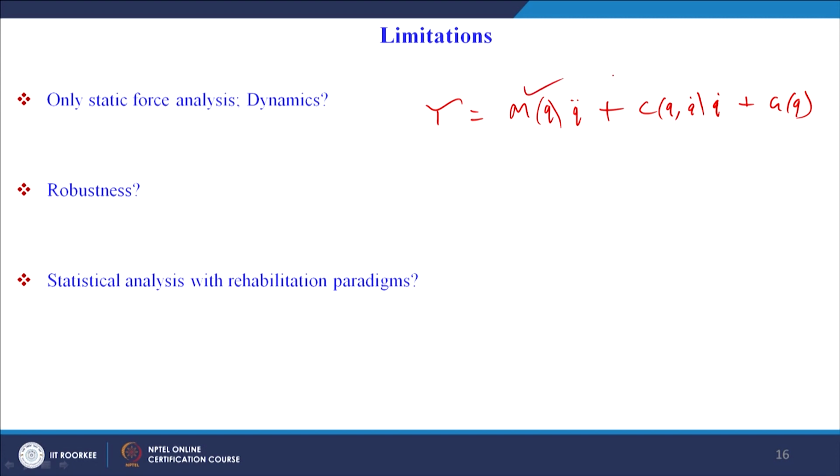We need to consider the inertia matrix, the Coriolis matrix and the gravity term in order to obtain the joint torque, but what we have considered through ideal dynamics is q dot. With this we defined our system control strategy, whereas actually the highly coupled dynamic equation must be considered, with the inertia matrix, Coriolis matrix and the gravity term coming into the picture.